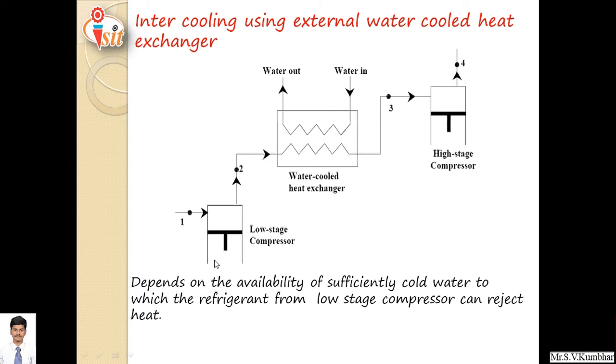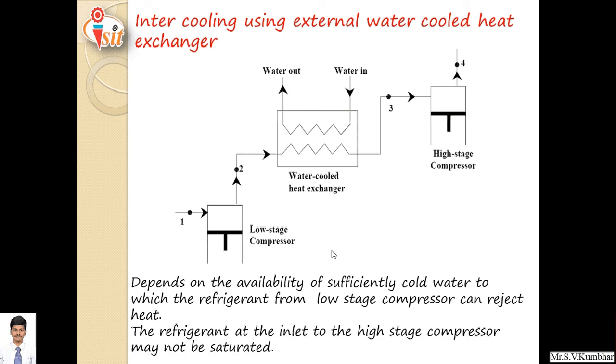This depends upon the availability of sufficiently cold water to which the refrigerant from the low stage compressor can reject heat. The refrigerant at the inlet to the high stage compressor may not be saturated in this case.